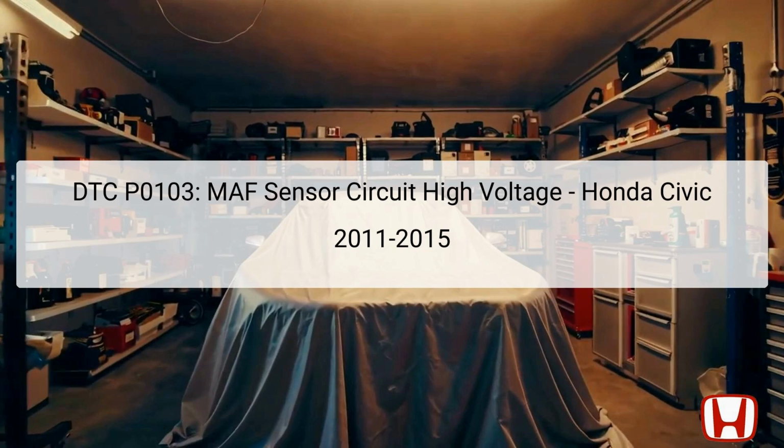When the MAF sensor detects high voltage, it can mislead the engine control module, ECM, resulting in performance issues or increased emissions. In the Honda Civic from 2011 to 2015, the MAF sensor is typically located in the air intake system just before the engine's throttle body. Troubleshooting this DTC accurately is essential to ensure the engine runs optimally. Before proceeding, it's recommended to review the general troubleshooting procedures outlined for diagnosing such fault codes.